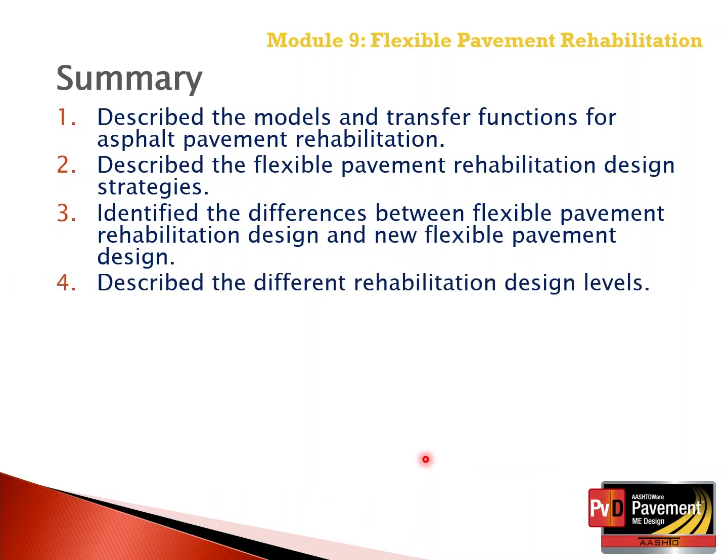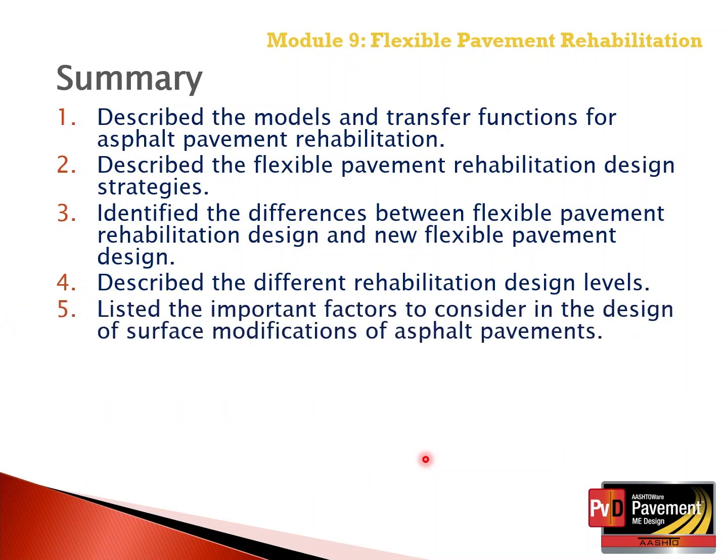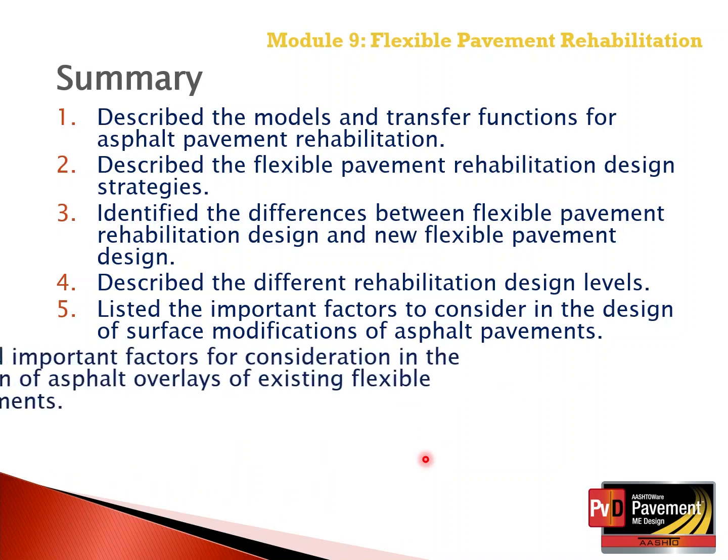We also described the different rehabilitation input levels, both for flexible pavement rehabilitation designs in terms of asphalt overlay versus concrete overlays. We listed the important factors to consider in the design of surface modifications of asphalt pavements using the Pavement ME design software.